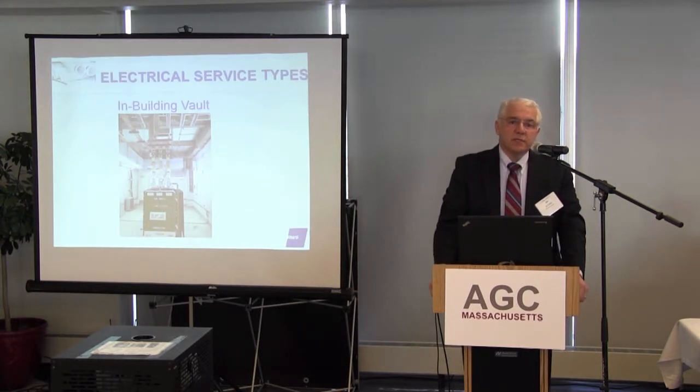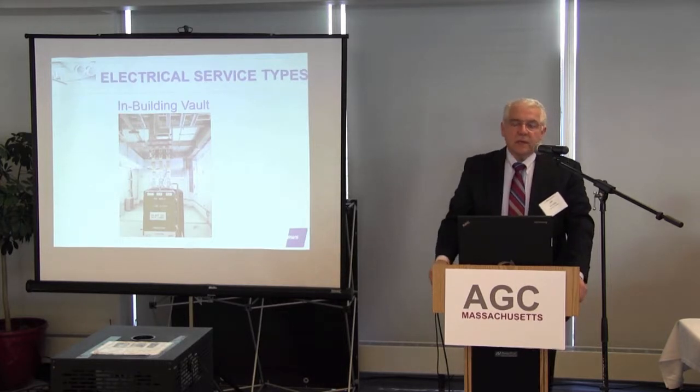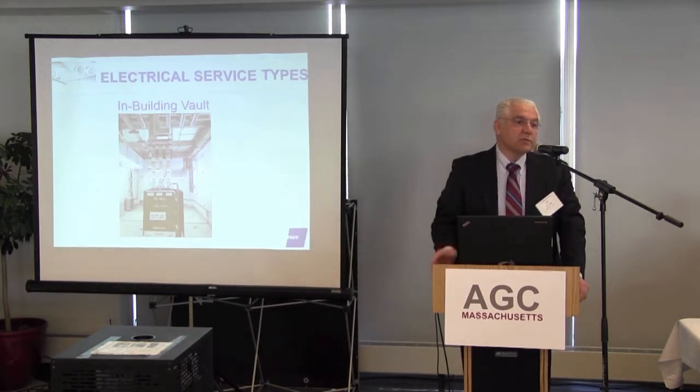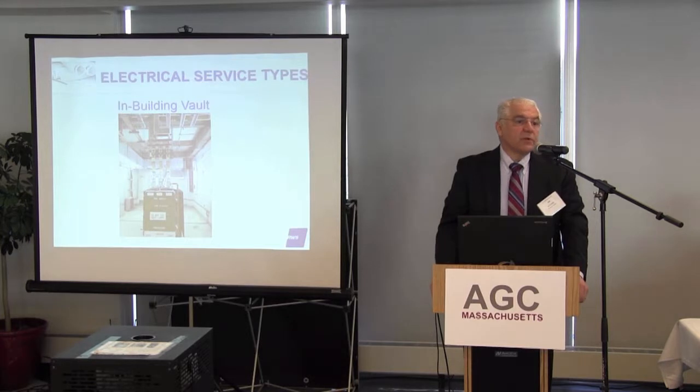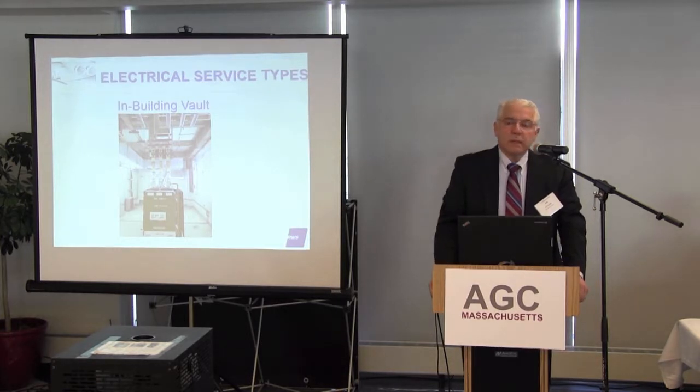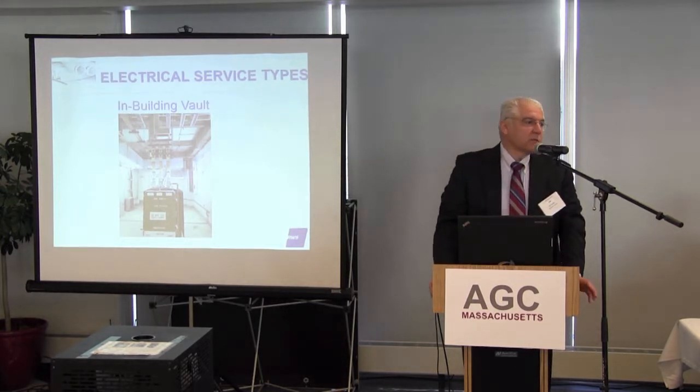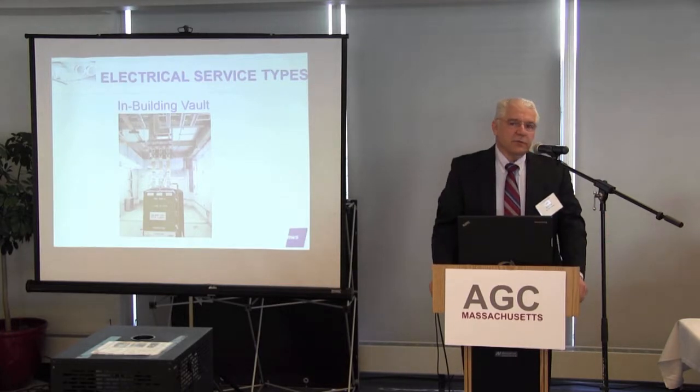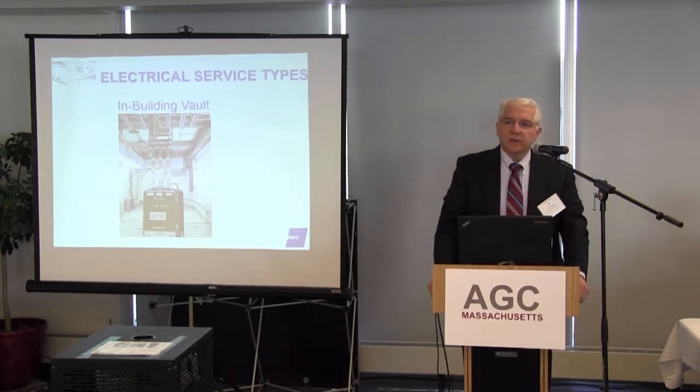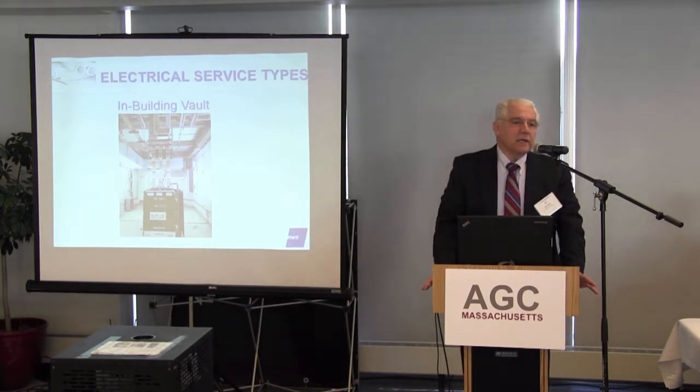The other thing is when you're dealing with the utility company with underground distribution like the primary conduits to a transformer, your civil guy does the excavation, and the electrical contractor puts in the conduit. Before anything can be covered, not only do you need an electrical inspector's approval, but you also need the utility company's approval.